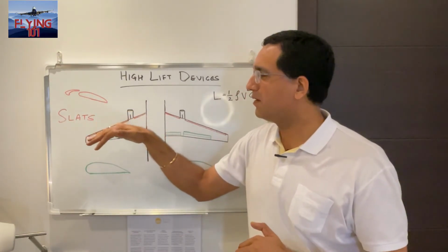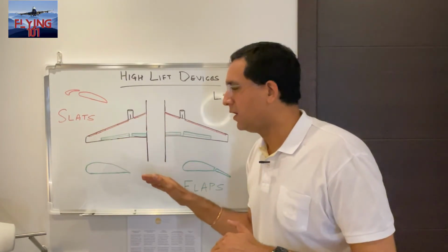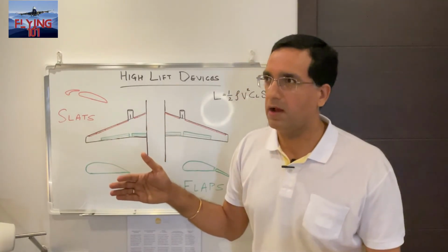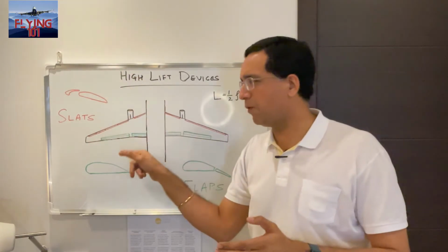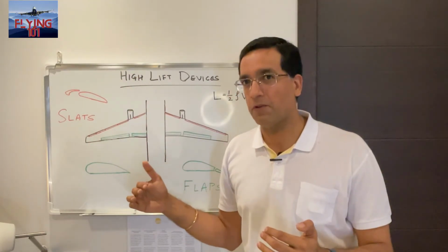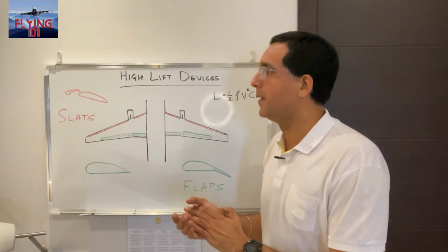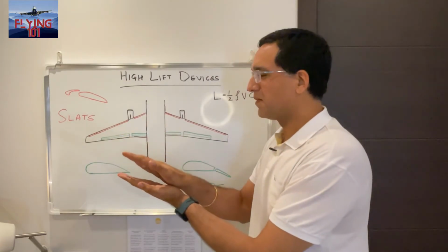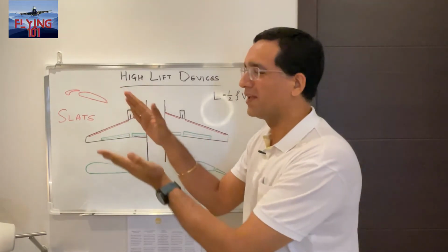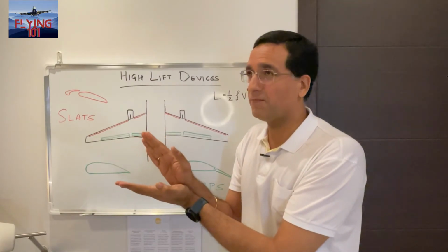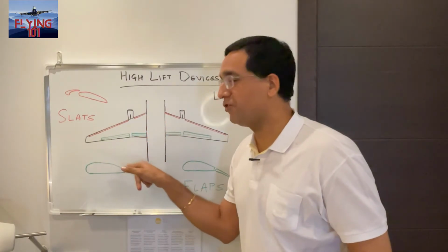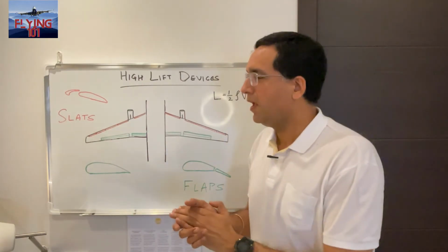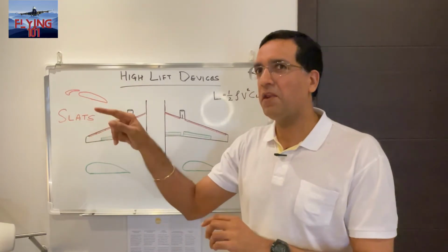So when we're talking about a smooth airflow over the wing, in normal conditions, we've got a smooth laminar airflow, therefore we have a boundary layer. It's like there's viscosity between the airflow and the wing, and that's giving us a pressure drop on top, and so lift is created. But if we didn't have the slats extended, and if we continue increasing the angle of attack, so the angle between the wing and the relative airflow, it would only be possible up to a certain angle after which a separation of the airflow would occur, and so the wing will no longer be able to generate lift.